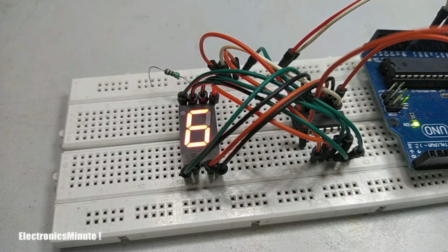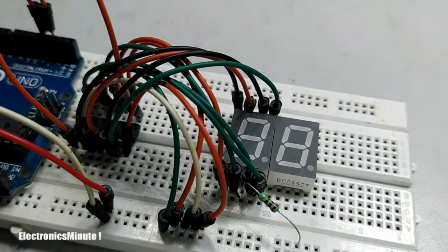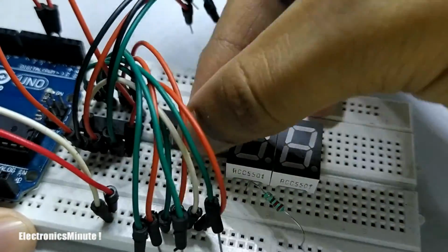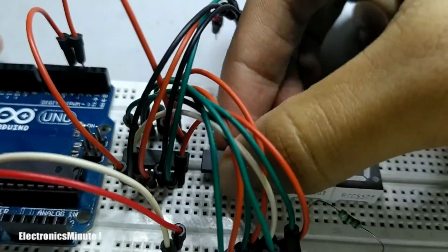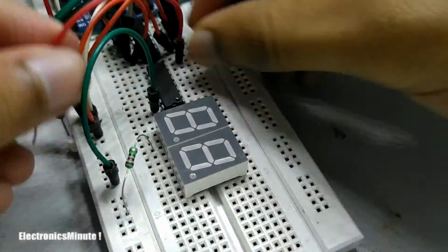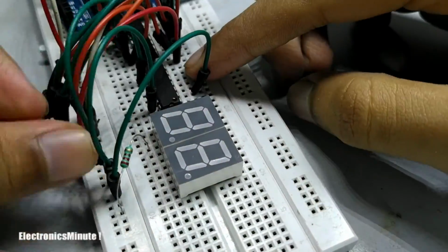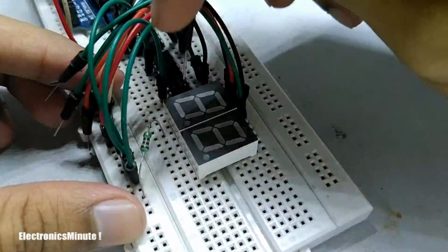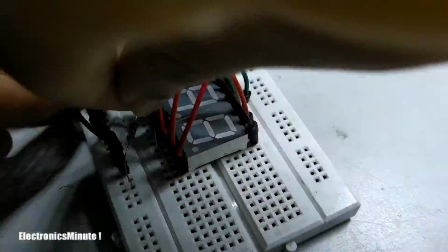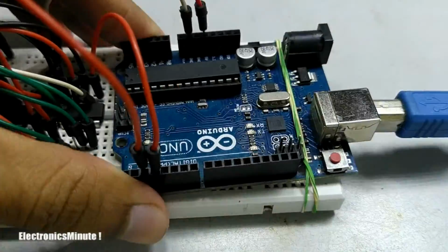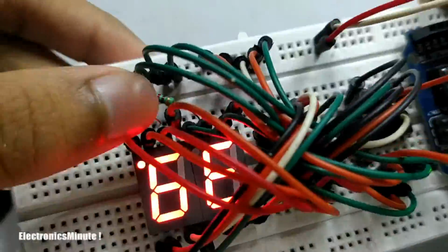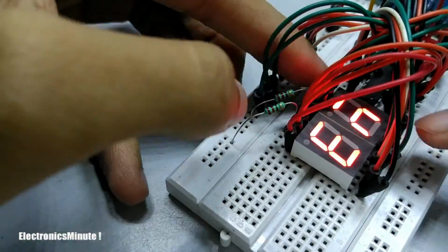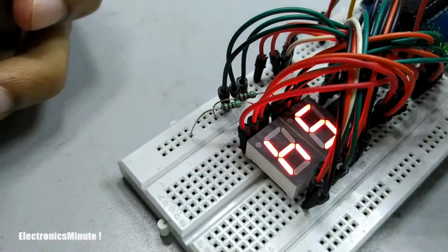And the interesting thing is now we can use a second unit, just using another 74HC164 IC, to completely display a 2 digit number. The connections of the IC are the same as before in this case, and no extra Arduino pins are required. The input pin 1 of the second shift register is fed with the output pin QH, the last data output pin of the first shift register, to make a continuous 16-bit long shift register.